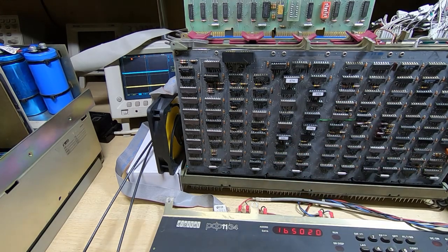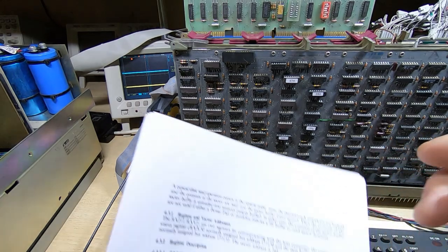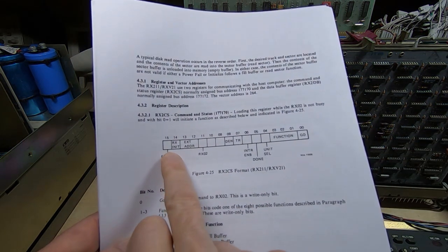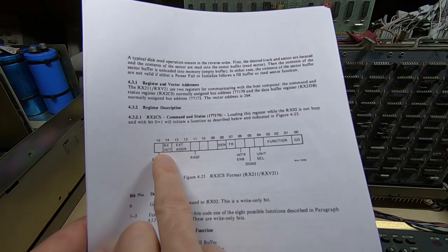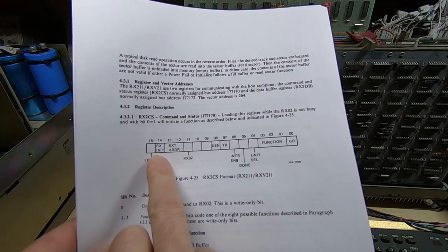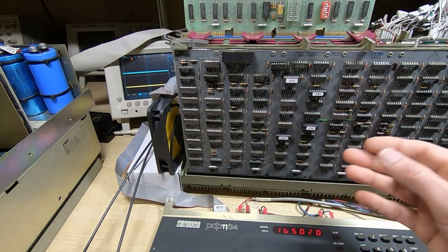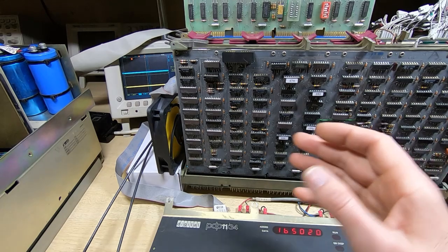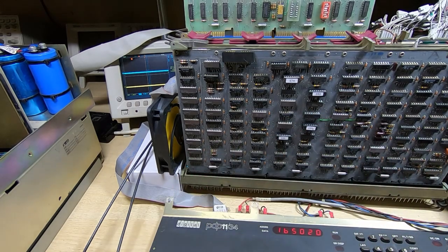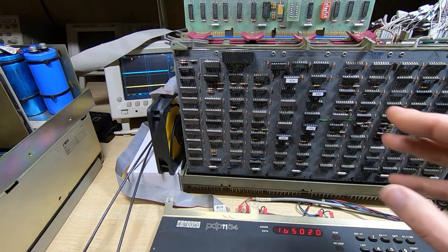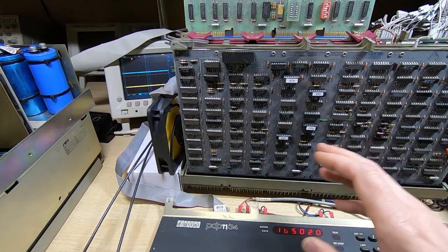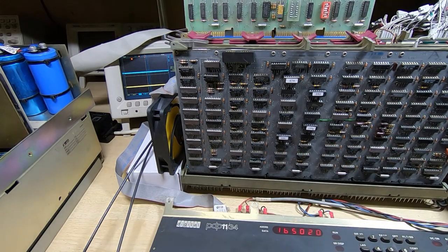So the first thing I generally do is send a reset command. If we look at bit 14, you'll see that it says RX init, and it's a bit like the reset you get on the backplane, except it doesn't reset everything else, it only resets the drive. Resetting the entire system doesn't tell us much because there's a hard-coded reset attached to the AC low input.